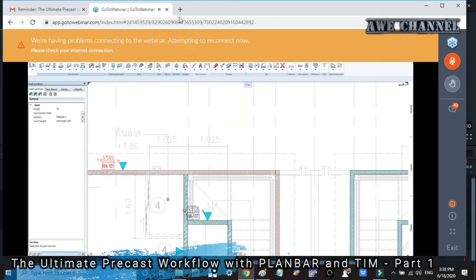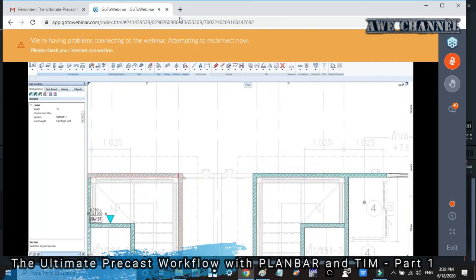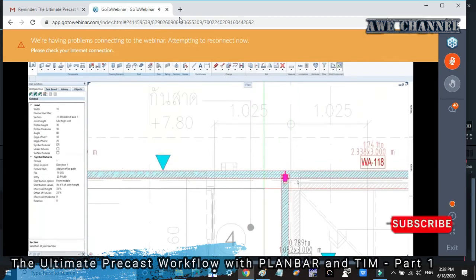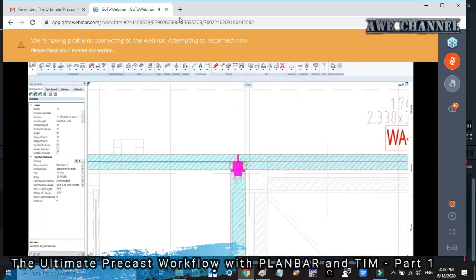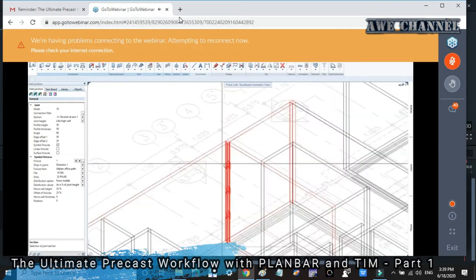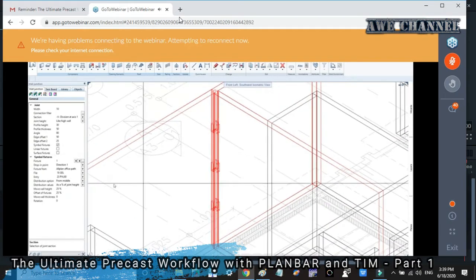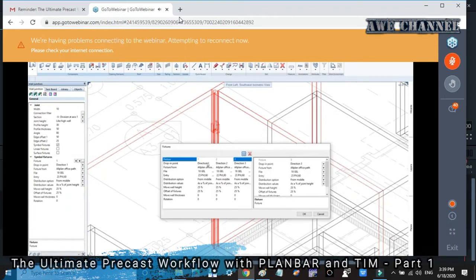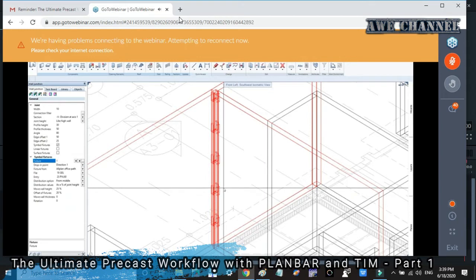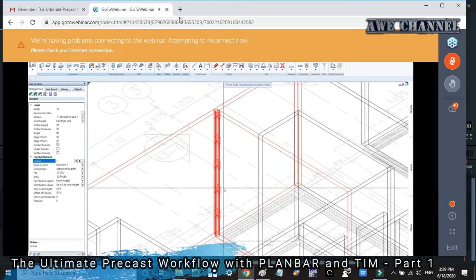And the connection here is not fixed actually, it's parametric. Let's say, for example, if I want to have a connection here, and this is actually the three-direction connection, and you can see now we have 3 wire loops. If I want to have 4 wire loops, it's very easy actually, because it is parametric. You just select and change offset to 20, and now you get 4 or 5 connections, depending on your parameters.